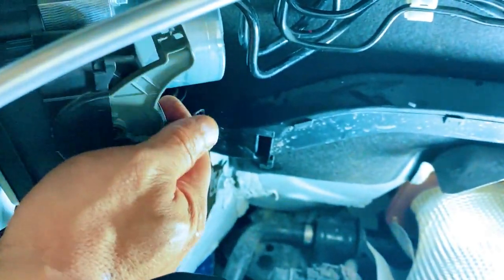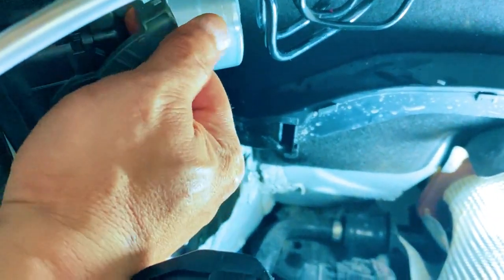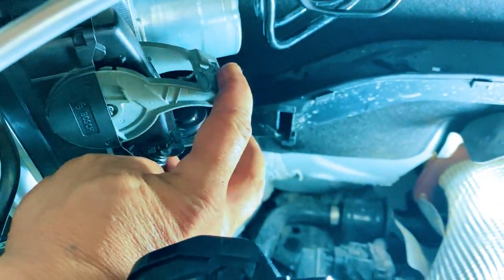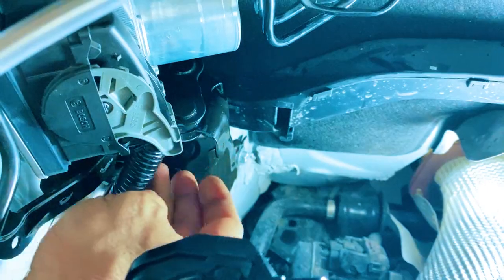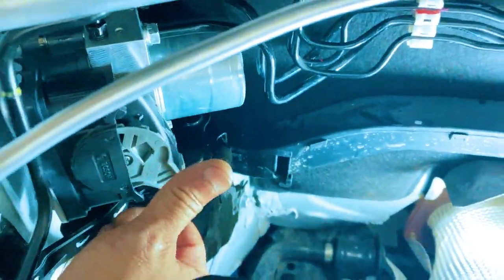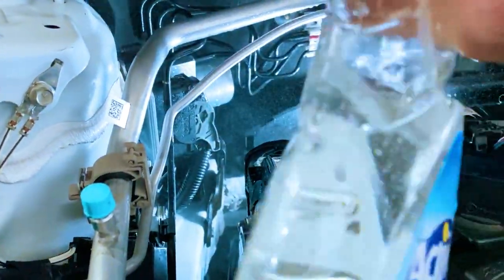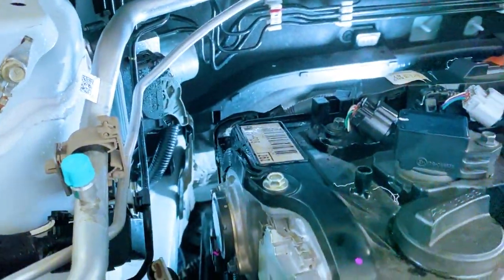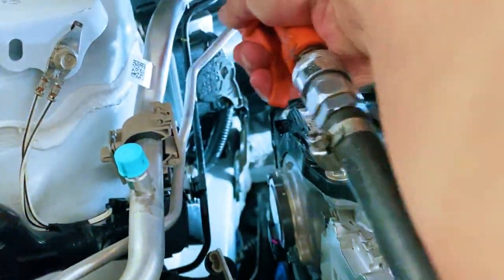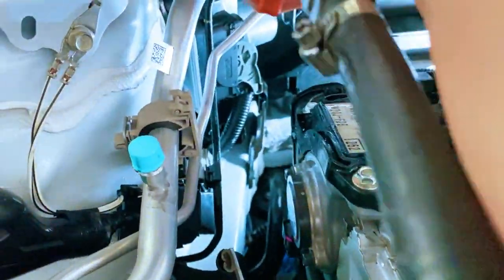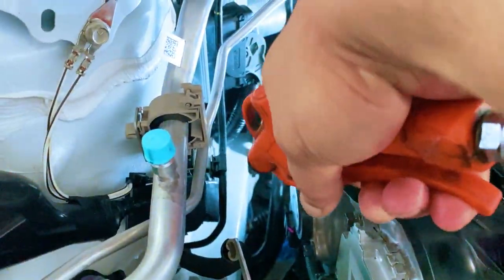8:35. Remove the actuator. Now we can remove the mounting hardware securing the brake actuator assembly. Remove the specified nuts and bolts and carefully take the actuator and bracket out of the vehicle. Once the assembly is removed, separate the actuator from its bracket according to the Toyota procedure. At this point, the old brake actuator is completely removed.